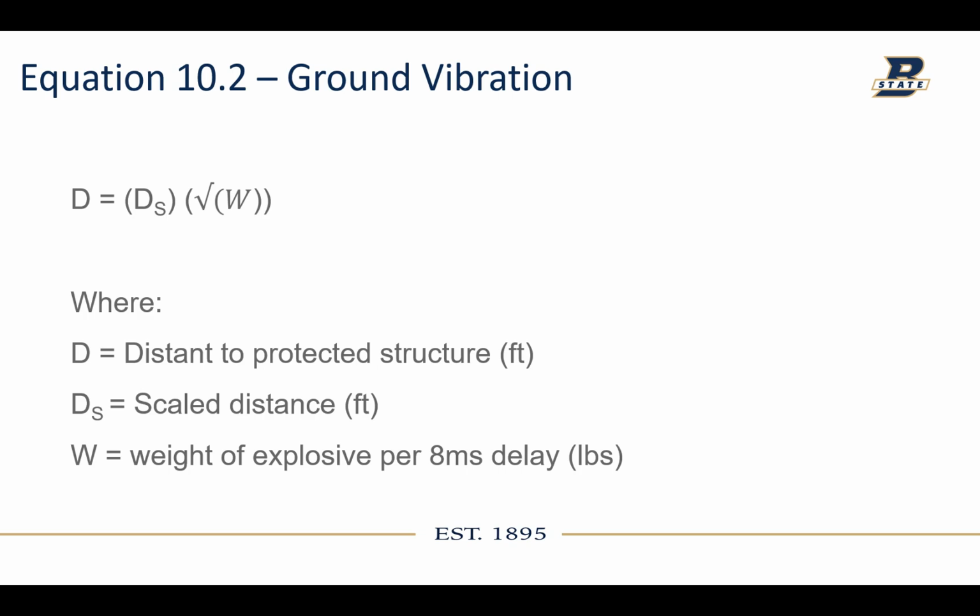But anyways, your ground vibration. So to calculate the distance to protected structures, you need to know the scaled distance, and then the square root of the weight of explosives per 8 millisecond delay. So we need to know all of those.